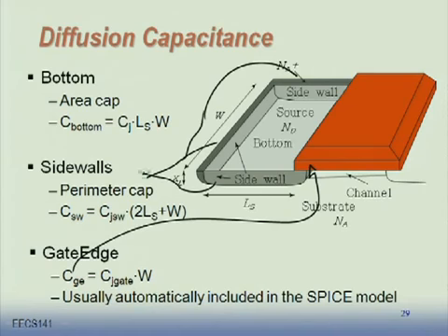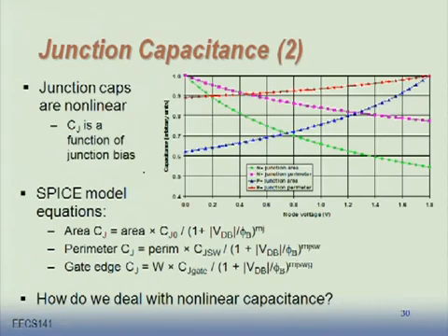The bottom line is this is all nonlinear. So when you're looking at these junction capacitances, this is capacitance versus voltage. It's a C junction as a function of bias. I'm not going to dive deep into that, but what you find out here is that all of them in SPICE are nonlinear, and as Arko has said, he was correct. It's a junction capacitance divided by 1 plus bias voltage divided by some built-in potential to the power of mj.